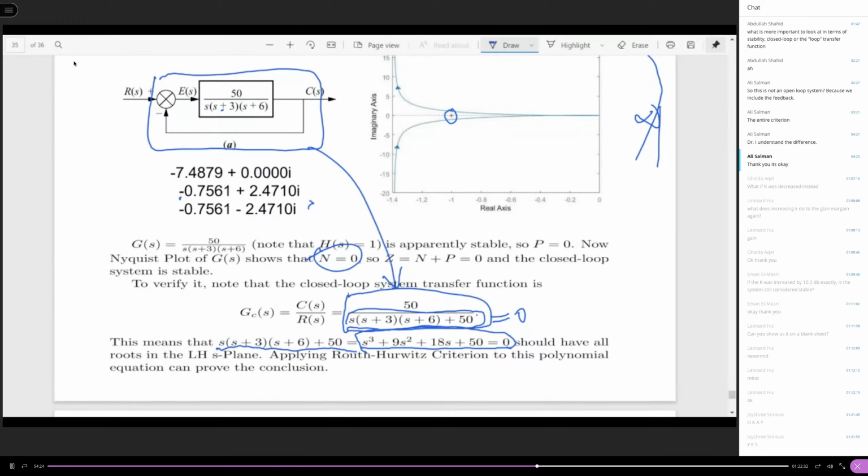The Routh-Hurwitz criterion can actually be applied to evaluate any polynomial equation. But when we come to the control system, if we want to use it to identify the closed loop system stability, we have to figure out the closed loop transfer function's denominator polynomial equation.